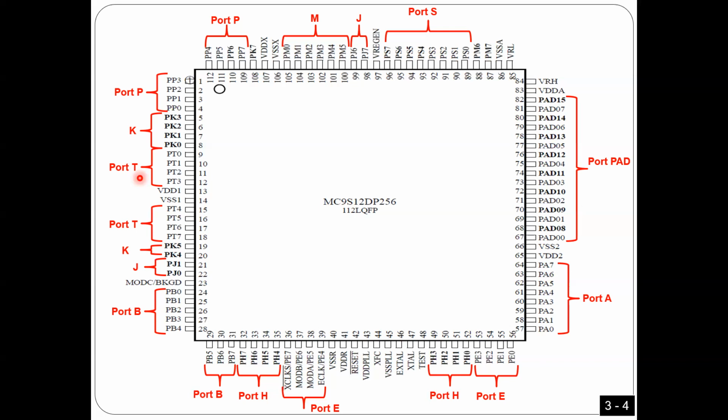The electronic circuit has to be connected this way because it's input, right? If it is output, that means the current has to go this way, right? Can you see, okay, guys? So it has to be connected this way. What I'm saying is that they made this microcontroller so that every pin or every port can be programmed as input or output, and it's up to you.